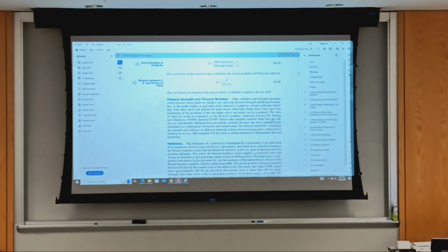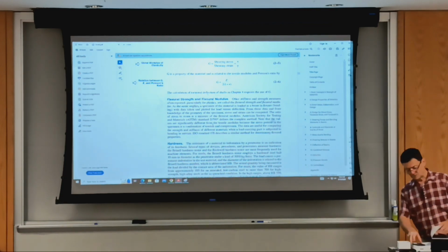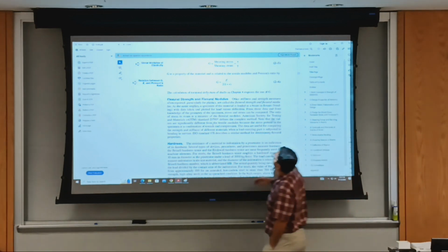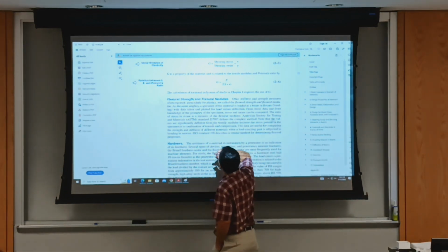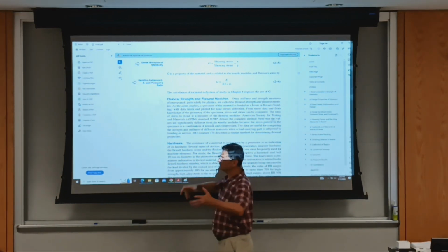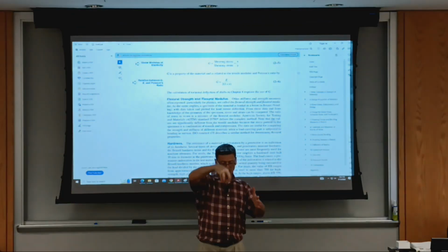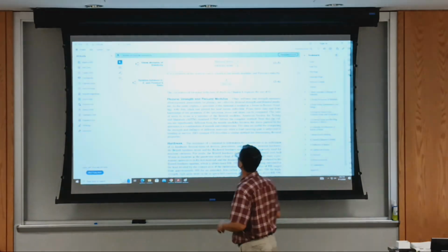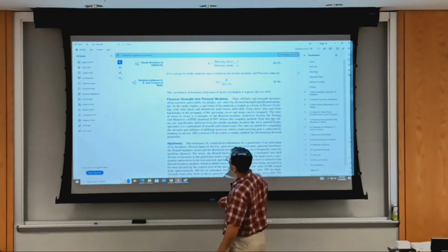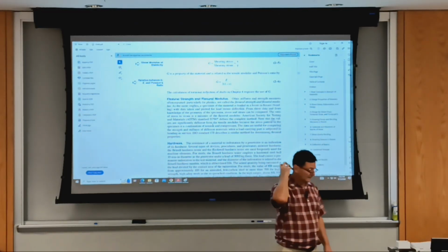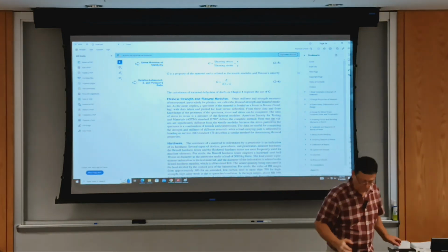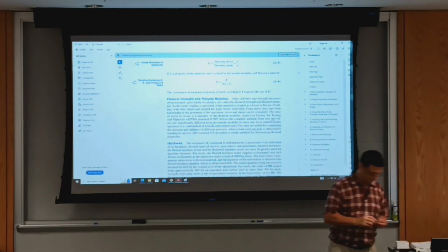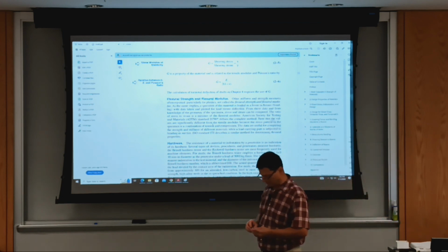There are flexure tests done to assess the properties of material. That's done on plastics and elastomers, wood or concrete beams. You support it and you apply a load in the middle, and you record deformation as a function of load applied. And then there's another property, likewise important for design work and in applications.